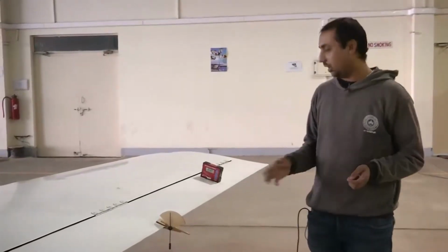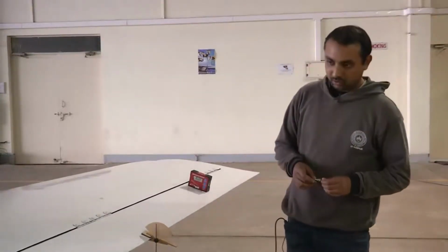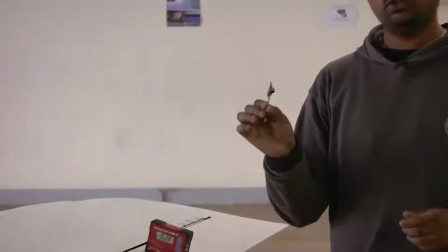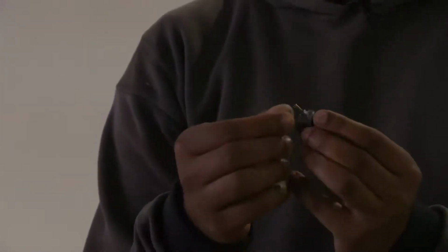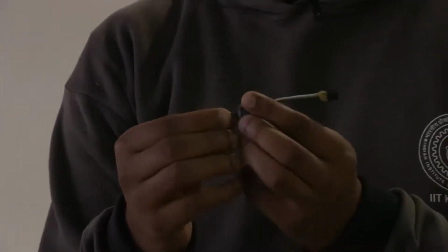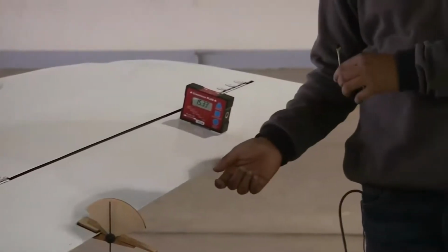Now, how this voltage was calculated, we showed that during the setup of experiment we required an inclinometer, a potentiometer, a laptop interfacing software, and a data acquisition system, that is NIDAC we are using. Now, this is a small potentiometer, not used in this particular application, but as I told, it had 3 terminals. These are the 3 terminals. This is a rotating contact switch. On varying this, you can vary the voltage between these particular 2 pins. And the same principle you can apply while calculating your voltage for deflection of this control surface.